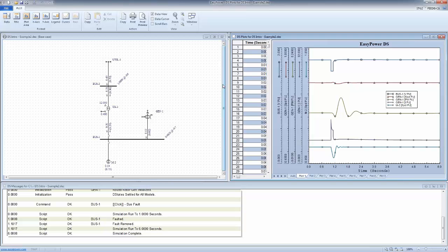As I went over a few examples, you can run a load flow. It's going to give you the final results, or the steady state point of your system. If you run a short circuit, it gives you the final results, and I don't know if this is the exact technical term, but it gives you the result as if the short circuit stays there forever, and how much short circuit current is going to go through different sections of your system.